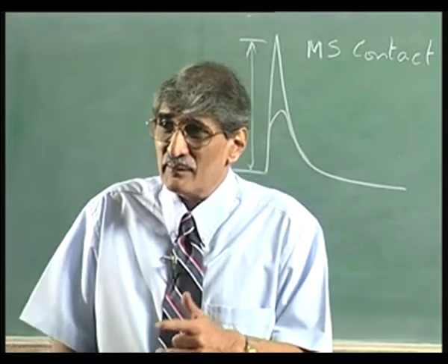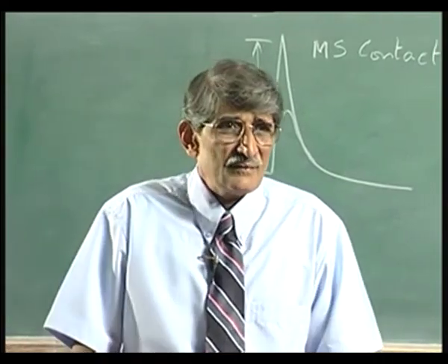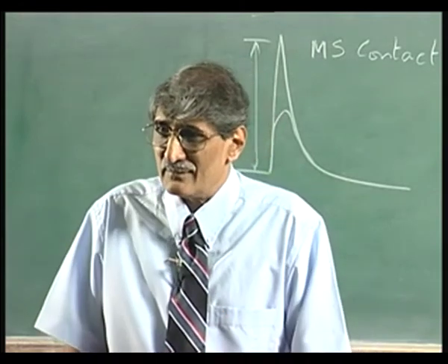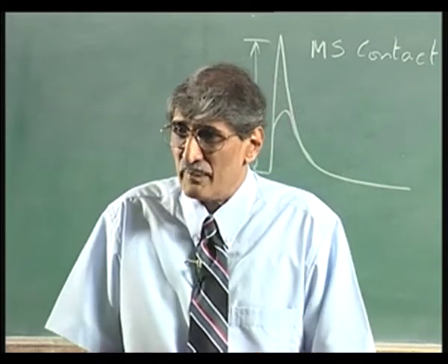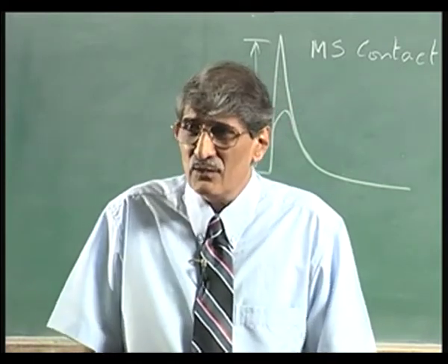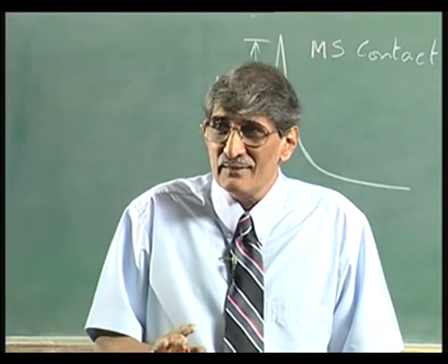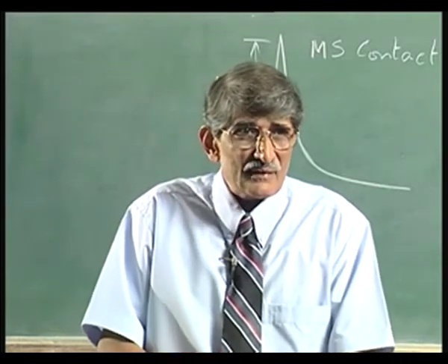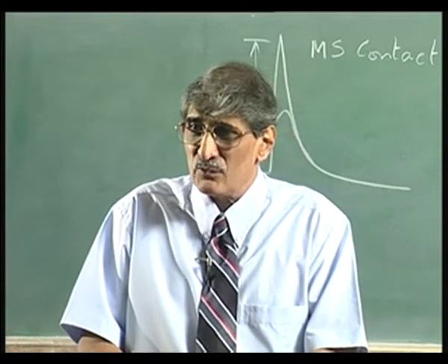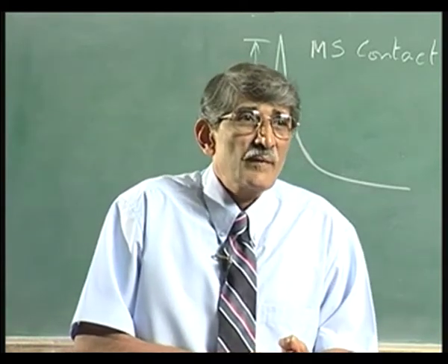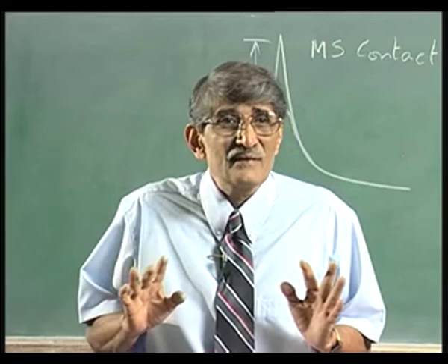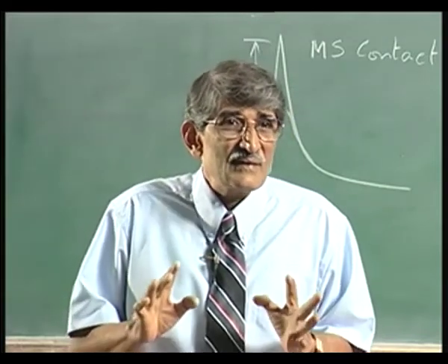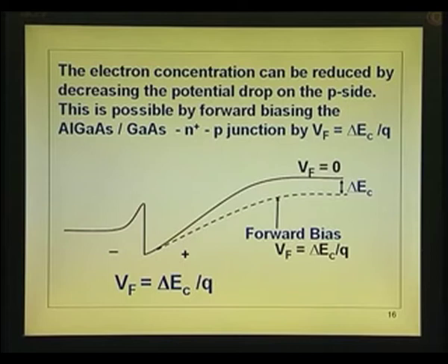You put x equal 1, aluminum arsenide, that seems to be unstable. You tend to lose arsenic from that. So, that material itself is unstable when you just keep it open, or even raise the temperature slightly. With all those restrictions, worried about the trap centers, worried about making ohmic contact for source and drain, and also the stability of that layer, from all those considerations you say, okay, x of 0.3 is sufficient for me, it gives me a fairly decent MOSFET. It is not enough if you are the MOSFET. You must be able to control the